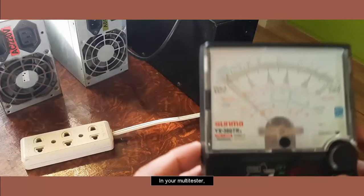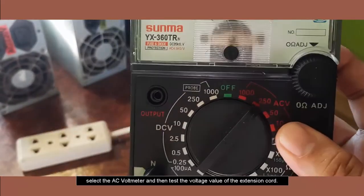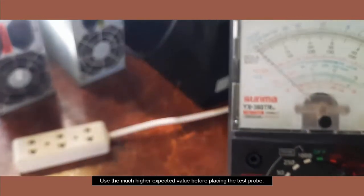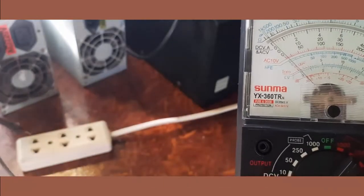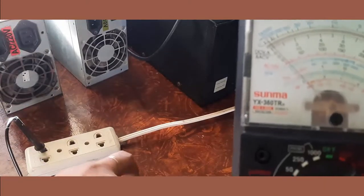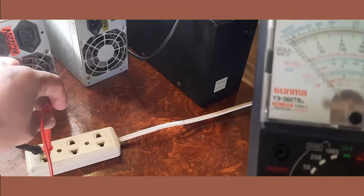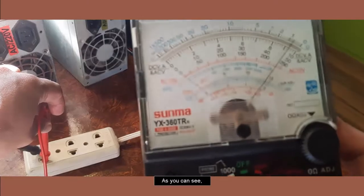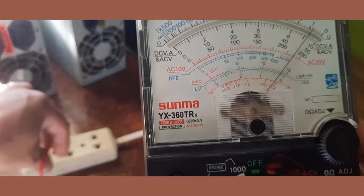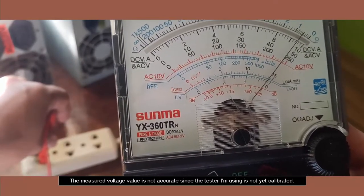In your multitester, select the AC voltmeter and then test the voltage value of the extension cord. Note, use a much higher expected value before placing the test probe. As you can see, the value is most likely equal to 245 volts. Note, the measured voltage value is not accurate since the tester I'm using is not yet calibrated.